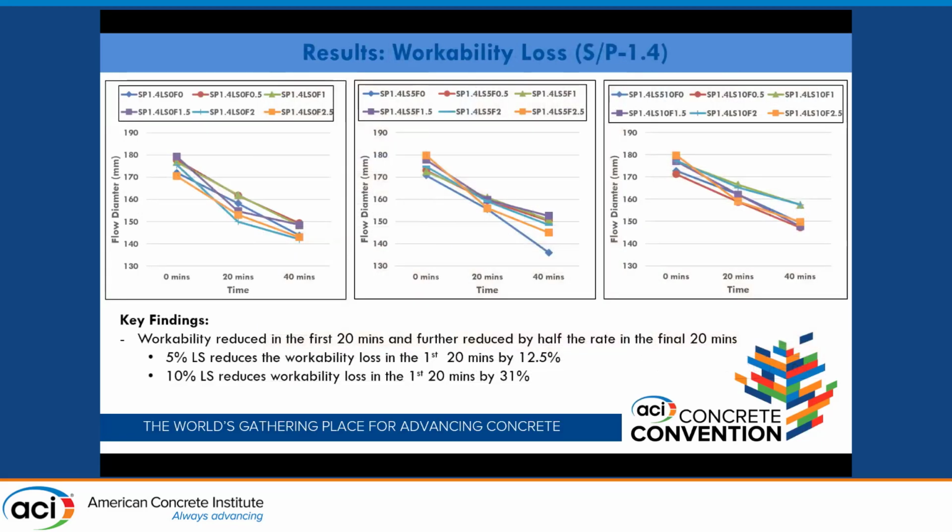To characterize the workability loss, this was measured at 3 different times after the mixing procedure, and we see that workability actually reduces over time. And here we can see the effect of limestone on workability loss: limestone addition actually reduces workability loss.